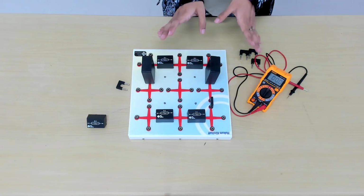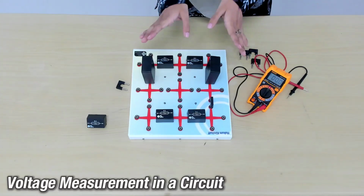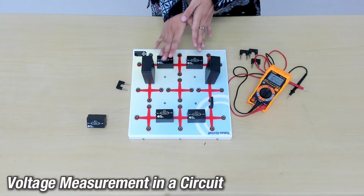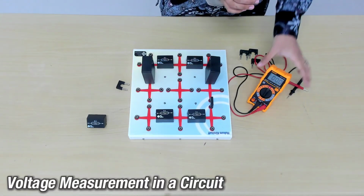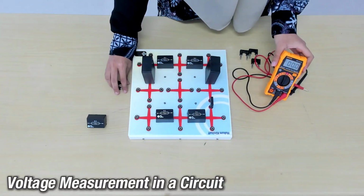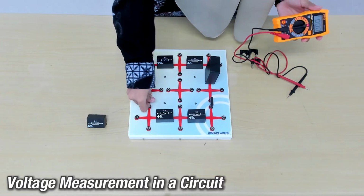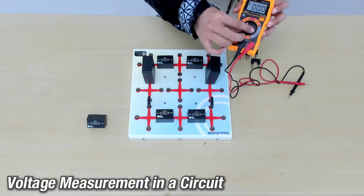To measure the voltage, we need to place the multimeter in parallel for each component. We will measure them one by one for each resistor 1, resistor 2, 3, and 4. Before that, reattach the connector so the current can flow through the circuit. Do not forget to turn the multimeter dial to the DC voltage.